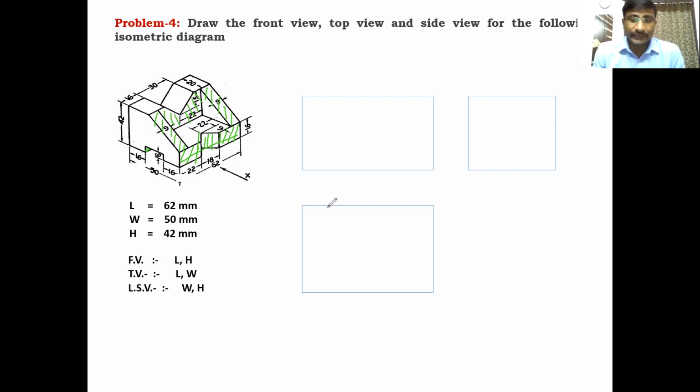So these are the visible surfaces. Clear? You must insert these surfaces into the front view box. So starting from one corner, this is the dark line, and the V-shaped block is also a dark line, which will be visible as a straight line here, and the continuous dark line. So the bottom line is a continuous dark line, and at a height of 16 mm is also a continuous dark line. It looks like a rectangle with two vertical edges at a distance of 22 from either side.